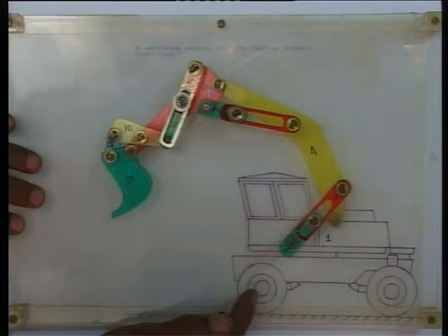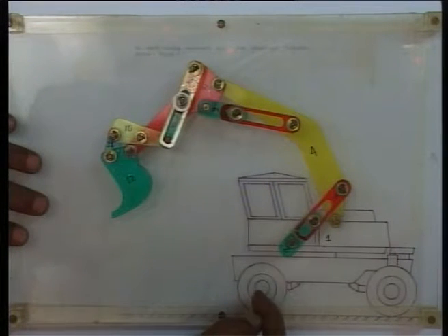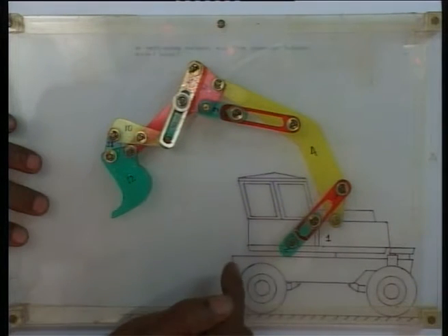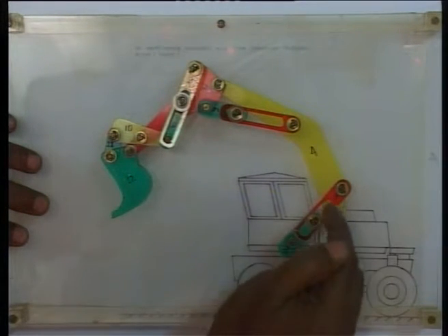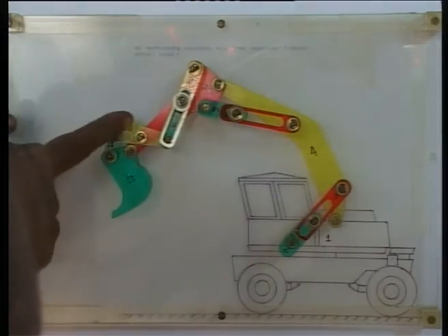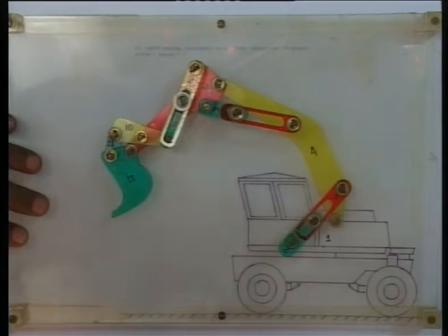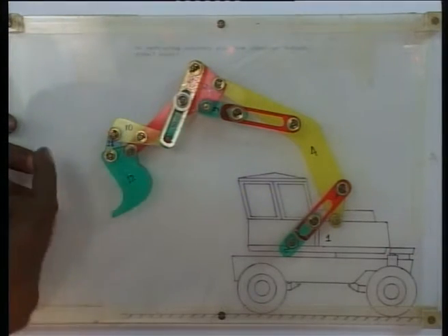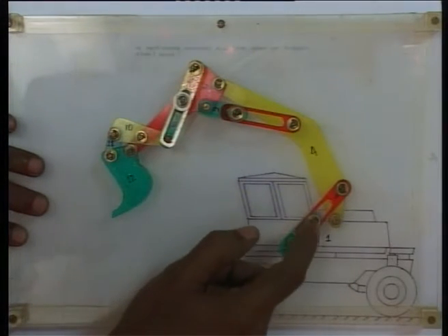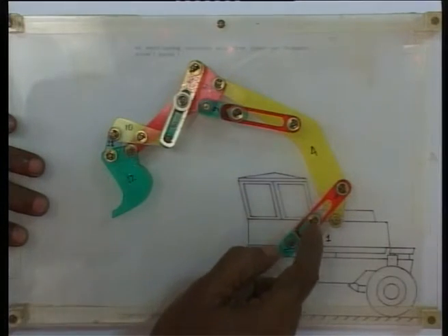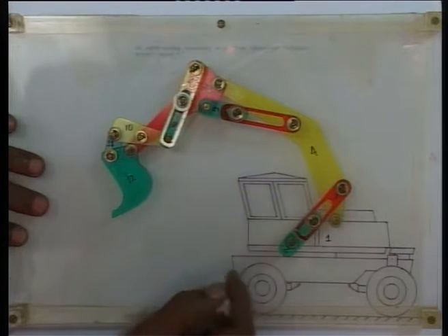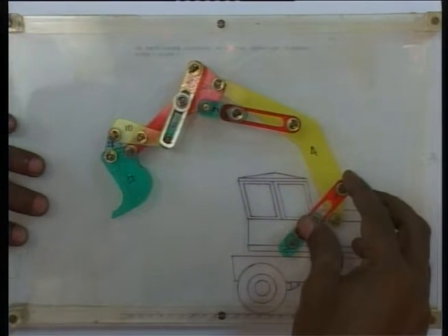As an example of a mechanism with 3 degrees of freedom, let us look at this model of an earth moving machinery. Here again, link number 1, the fixed link, is the body of this truck, and there are 11 other moving links 2, 3, 4, 5, 6, 7, 8, 9, 10, 11 and 12. This 12th link is the output link or the bin of this earth moving machinery. There are 3 hydraulic actuators, that means there are 3 prismatic pairs here, the rest of the pairs are all revolute pairs. As these 3 hydraulic cylinders are moved,